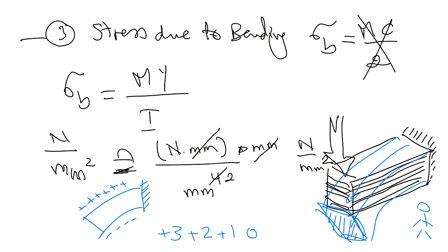You can see, guys, that the highest tension stress is located at the upper layer. When you move inwards, in this direction, your tension stress is getting smaller. And the highest compressive stress is at the lower layer, and when you move in that direction, your compressive stress is getting lower. So imagine that you are moving from positive 3, positive 2, positive 1, and then you will pass by a layer which will not stretch out, and it will not contract or compress. Do you get it?